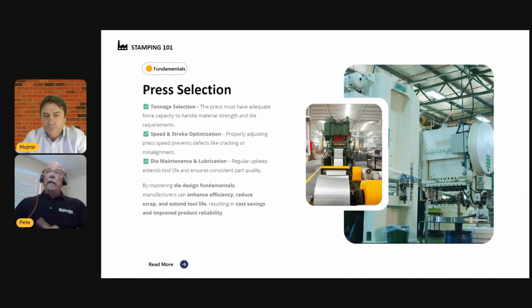We need to expand our view of the press a little bit more to understand better. It has other capacity limitations aside from how much force it can develop to make a part. One of these capacities is the capacity of the press to absorb reverse energy, or sometimes we refer to it as negative tonnage. This is the energy that builds up if I'm blanking, and we see negative energy or reverse tonnage situations. We're blanking or punching thick, high-strength materials.